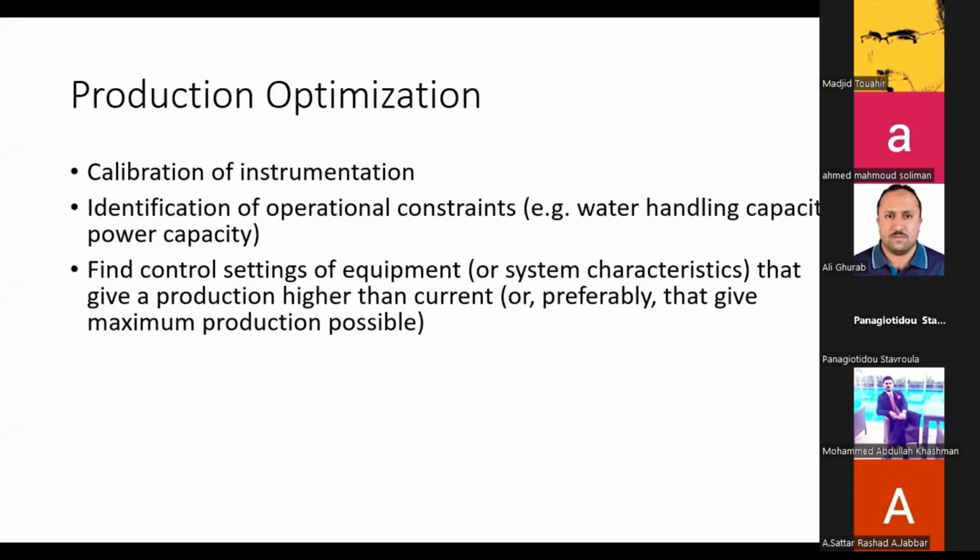some of the behavior of that injector around that producer, we have to do some measurement in that injector to see the effect of the injector on the producer wells, like running a PLT within the injector wells and within the producer, seeing the production profile and comparing to see what the impact is, if there's any impact or no impact at all.